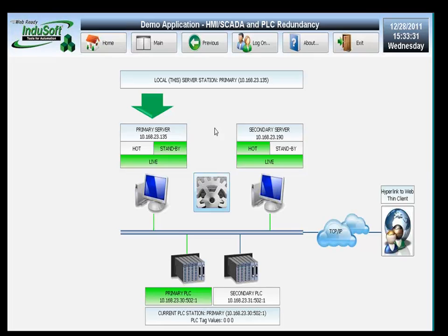and define different ways to define one station as hot or standby according to your architecture. And even though hot standby is a very typical architecture, in some projects you need more than 2 stations. You need 3, 4, 5. You need what we call a cascading system. Using the same type of script, the same kind of algorithm, you can create what we call a cascading redundancy. So if any station goes down, the remaining ones take over the duties from the other stations.